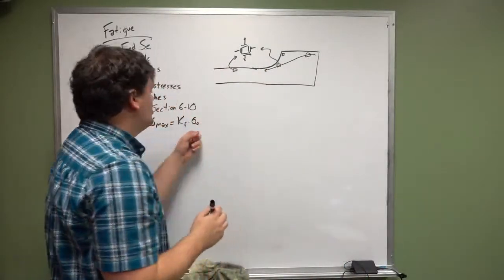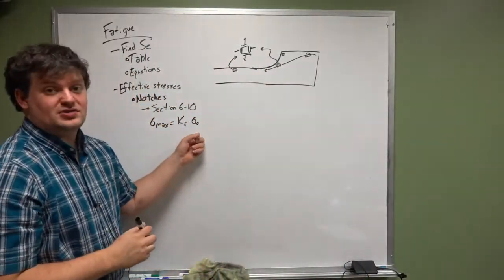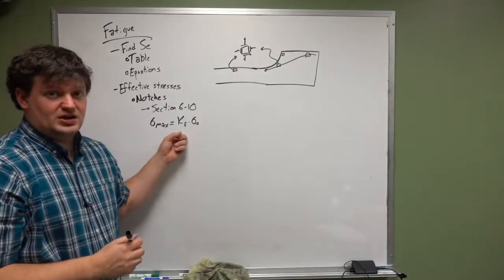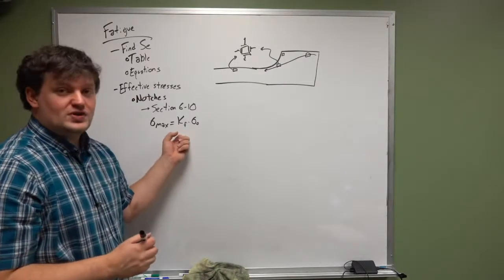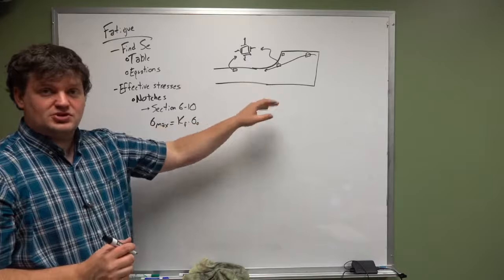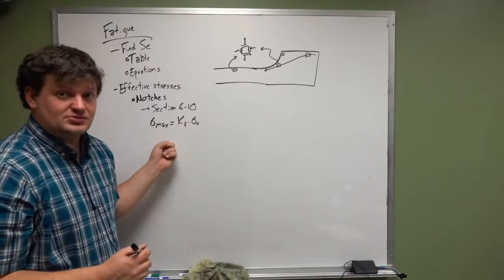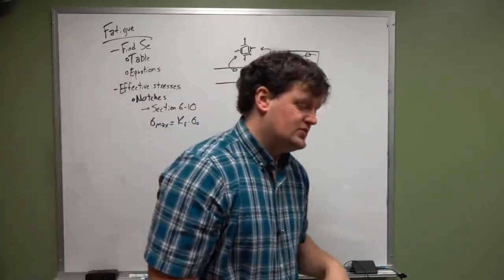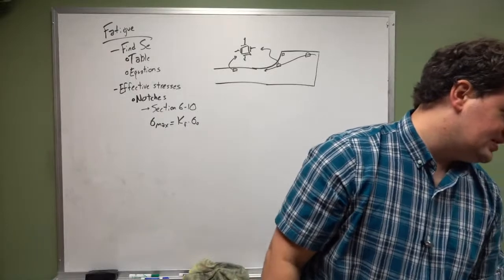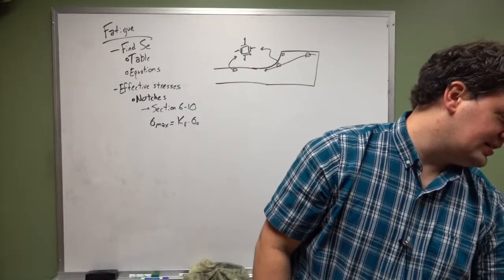So if you calculate your maximum stress value, you have to multiply it by some stress factor based on the geometry, and that's how you find your maximum stress.